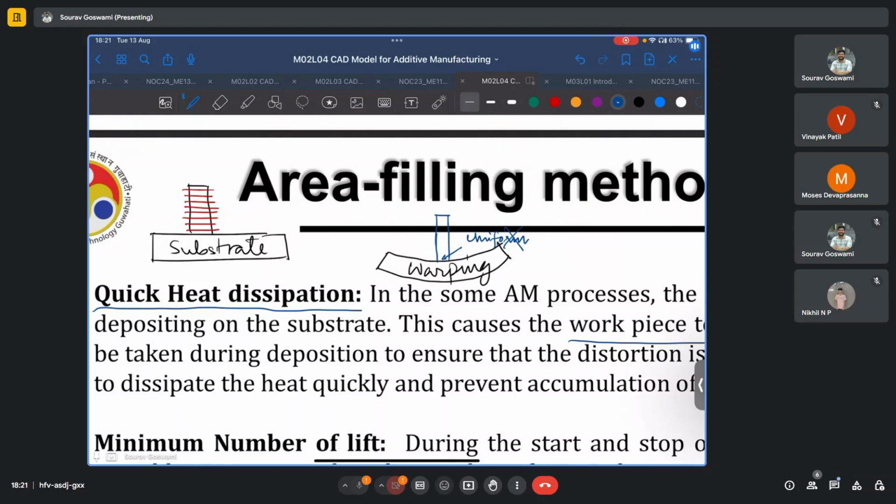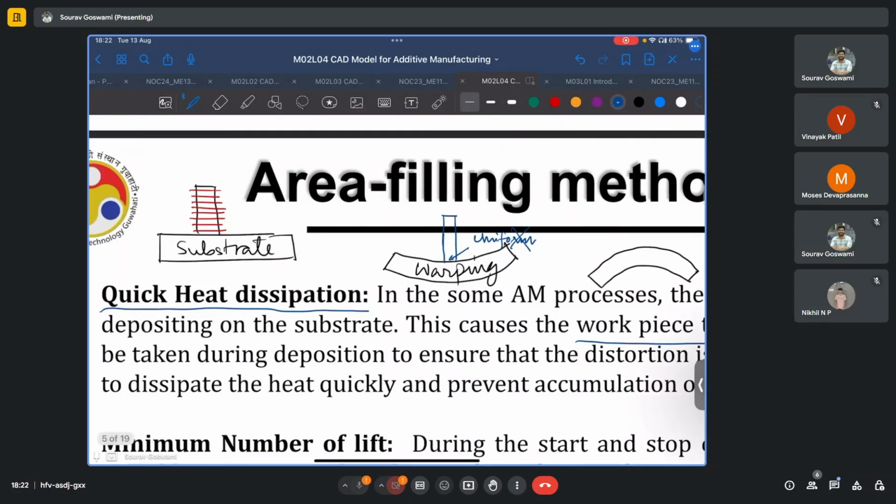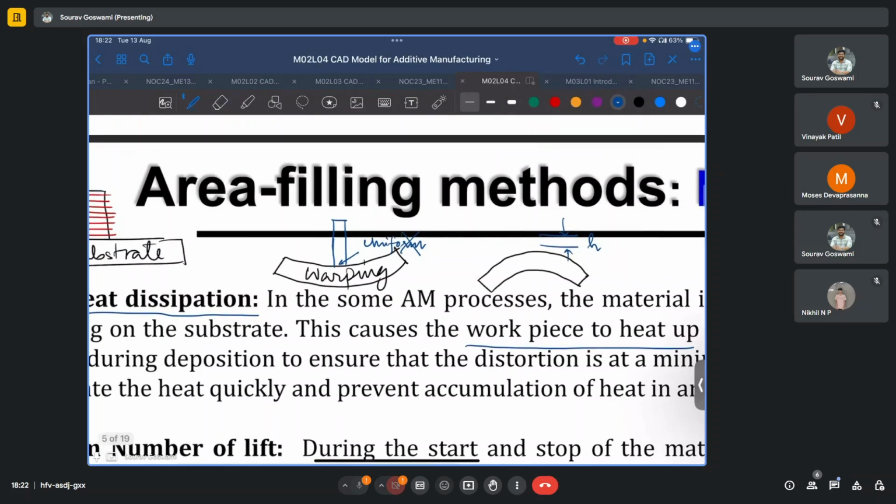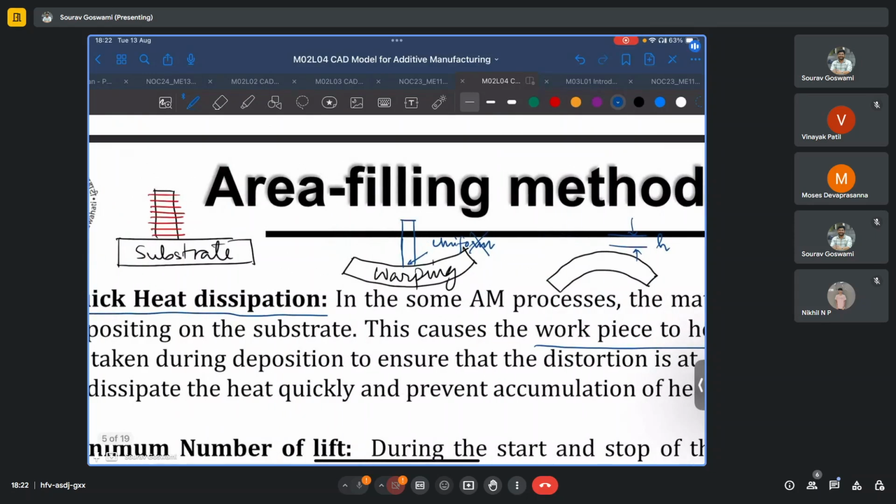And then, based on whether the center of the plate bulges up or bulges down, the further calculations that you already put in place for the movement of the deposition head or the height by which the deposition head will move in each successive print now no longer holds because it was relative to the base plate movement.